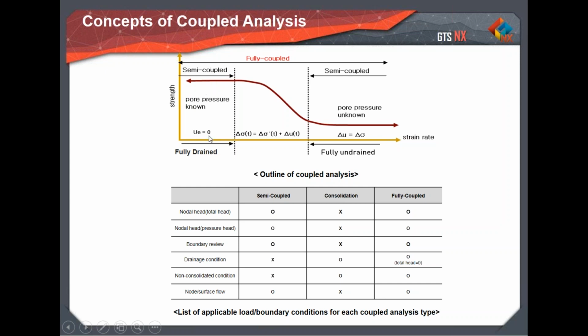But what we're showing here is that if you're doing semi-coupled, you cannot see the change in what would be even a drainage condition. So you either have to start a stage where the water is full or where the water is completely drained, and then switch in between. But then fully coupled, you can actually see that change over time, that stress-strain relationship over time. So you're not doing kind of like those big steps that are sequential if you were using that other method.